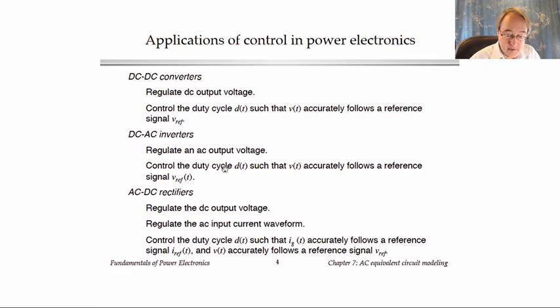Another case is an AC to DC rectifier, and we often now have requirements on our rectifiers that draw power out of the AC power line regarding the quality of their AC current waveform. In many locations, we're not allowed to build peak detection diode capacitor circuits that draw spikes of current out of the power line at the top of the sine wave. These pollute the power system with harmonics and disrupt the operation of neighboring devices.